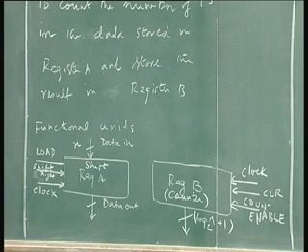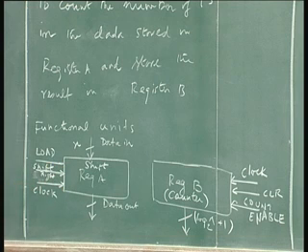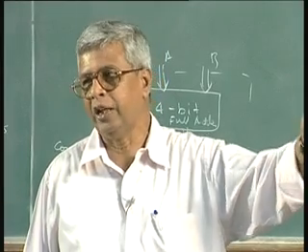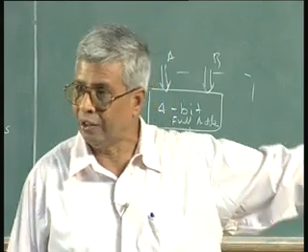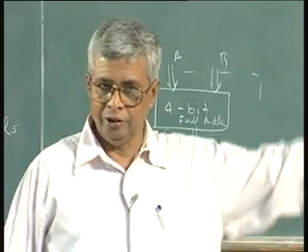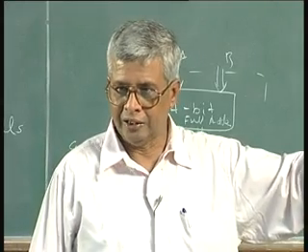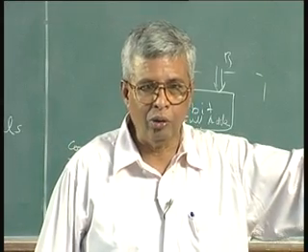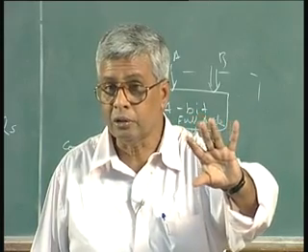So as of now I am defining 2 registers with architecture functional units. One register should be a shift register in which I will load the number, look at the LSB, if it is a 1 I will add 1 to the register B, if it is not I will shift it and again look at it and keep doing it till all the bits are covered. How I am going to do that, we have to think about it. It will all come in the algorithm. But now the first cut requirement I have to give now. So these are the specifications I am giving. I may have to change it a little bit.